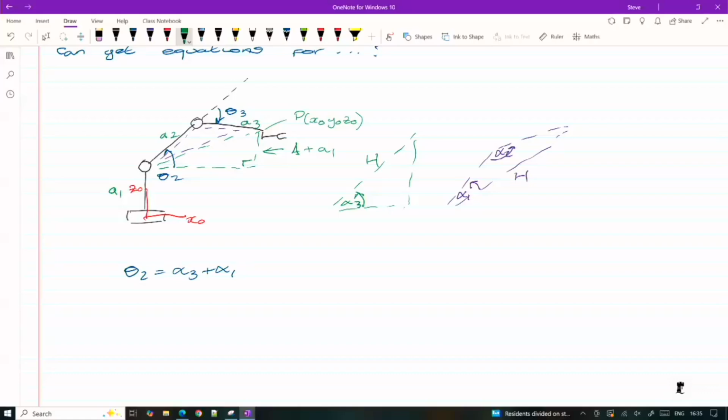So you just have to work out what extra rotations you need to apply to the joints. Within the Dobot Studio, which is how you control the Dobot, you can obtain the rest angles directly from that interface. So the Dobot will be posed and you can have a look within that interface and it will tell you what the angles of the joints are. And then just play around with it in the programming environment to get a feel for how the robot moves, just simply setting the angles or asking it to position its end effector at x0, y0, z0, for example, and seeing what it does.